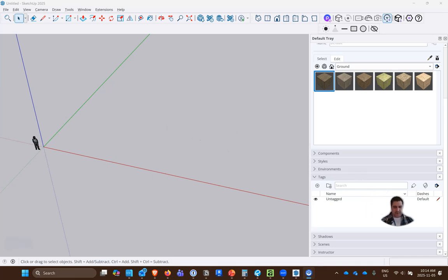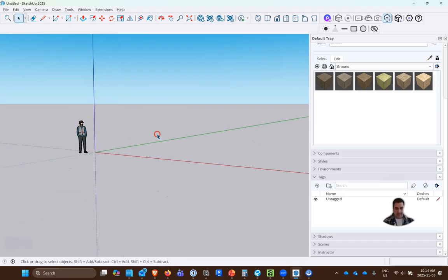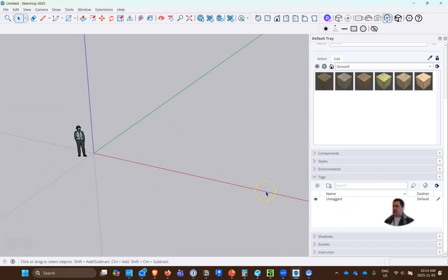So to start off in SketchUp, I already did create this, but if you want, you can use inches and feet or millimeters, whatever is best for you. Again, when you're typing in dimensions in SketchUp, you could type in 6 inches or 150 millimeters, and SketchUp will automatically do that conversion for you. So in some respects, they are unitless. So we have our SketchUp file set up.